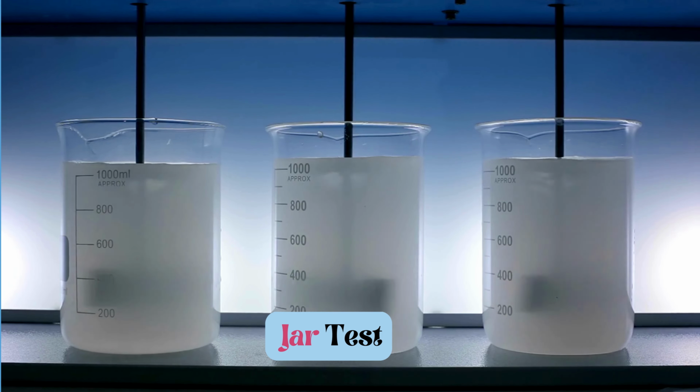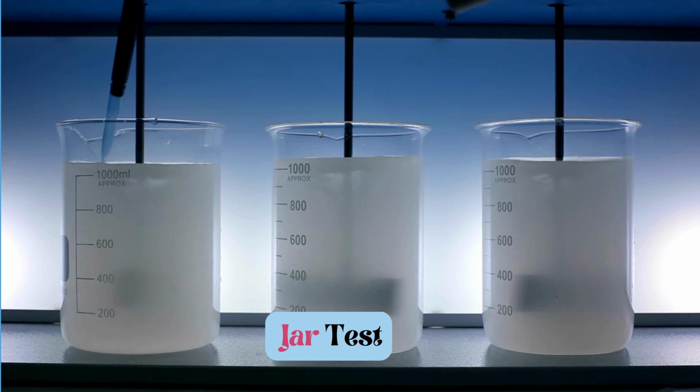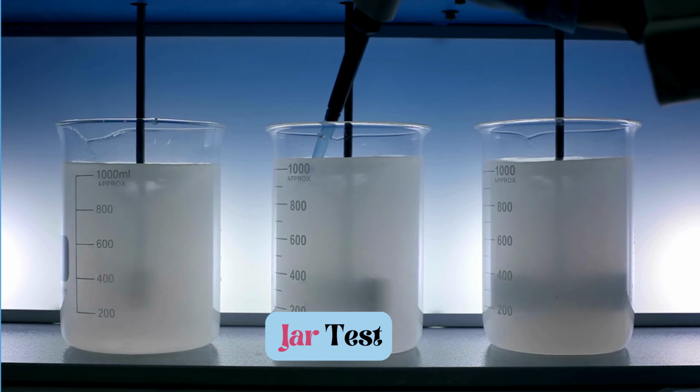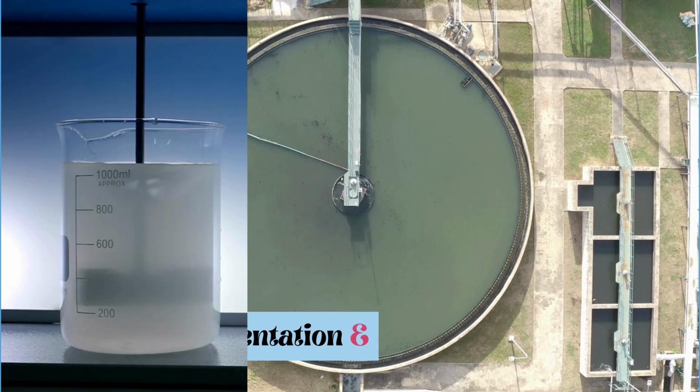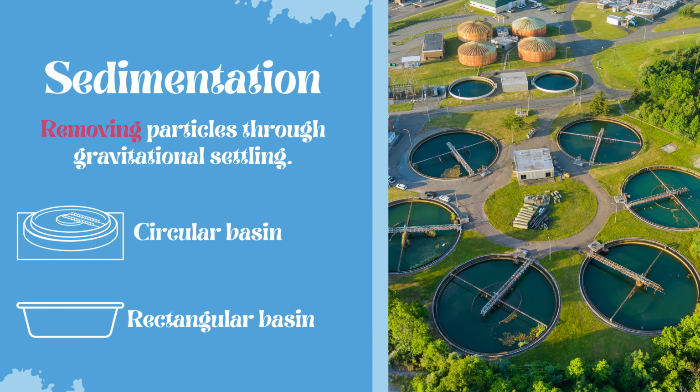Normally, we conduct a lab test called jar test. The idea is by adding different dosage and observing which one works best, we can ensure the dose meets the requirement effectively. Let's delve into sedimentation, also known as clarification. Sedimentation involves removing particles from water through gravitational settling. They are horizontal and circular types, each with its own advantages and disadvantages.